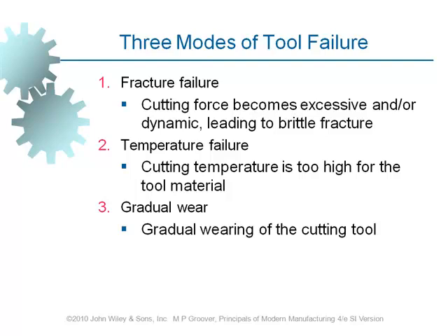For example, the surface finish will not be what we are after, the productivity will be reduced, and the magnitude of the cutting forces will increase. As a consequence, we will move away from optimum machining parameters. So it's time for us to replace the cutting tool.